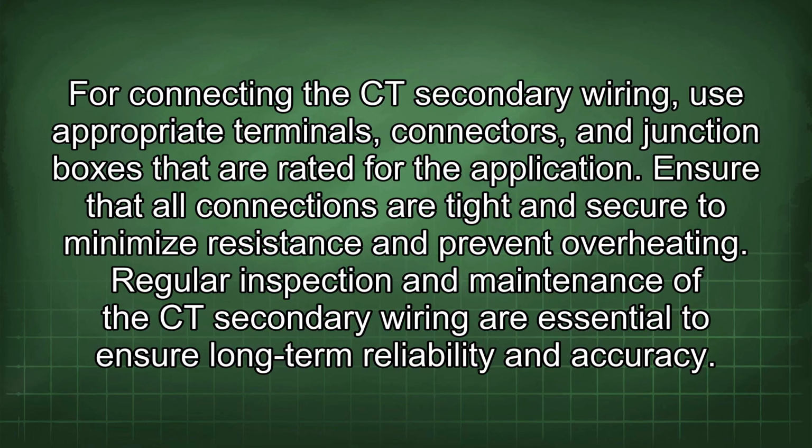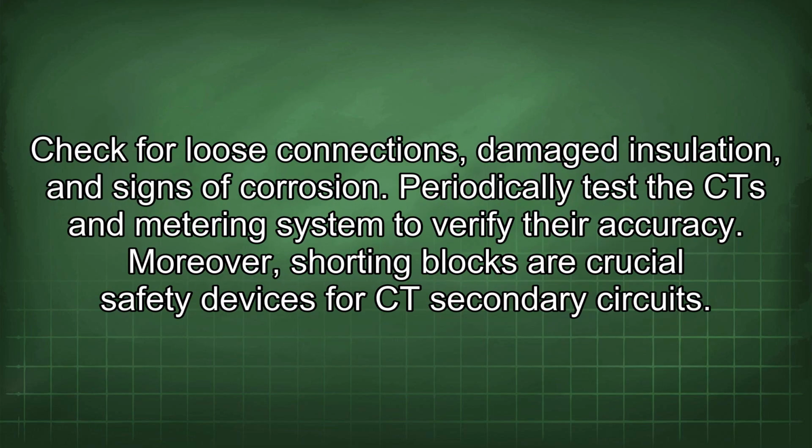Regular inspection and maintenance of the CT secondary wiring are essential to ensure long-term reliability and accuracy. Check for loose connections, damaged insulation, and signs of corrosion. Periodically test the CT and metering system to verify their accuracy.